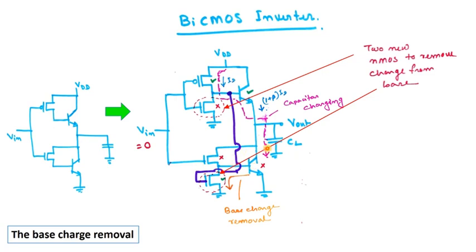This will be off because this transistor is off, so no base current here, right? It is now actually grounded. So this is off. So you can see there exists a path, though the current will flow through this bipolar junction transistor as well as through this NMOS and charge this output capacitor.